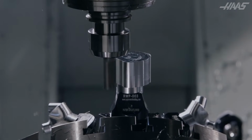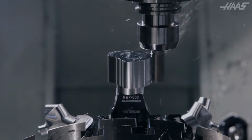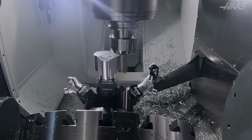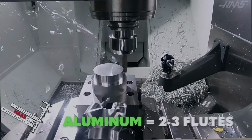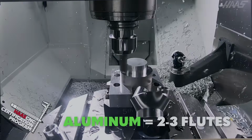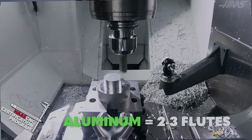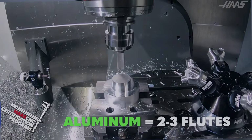For the most part, the 3 types of steel cut similarly, whereas the real big difference comes when we start talking about aluminum. So, end mills designed for aluminum have either 2 or 3 flutes. These end mills work well on aluminum because they have very large gullets with lots of room for aggressive cutting of chips. In a pinch, you could also cut mild steel reasonably well with these end mills.